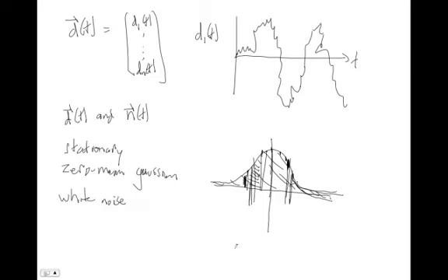So if you can approximate a mean and a rough variance of your noise, and then use these Kalman filters to choose your observer gains, the system it gives you will perform really well. It might not be completely optimal, but it'll be very close to optimal, and it'll still be a good approximately optimal system for you.